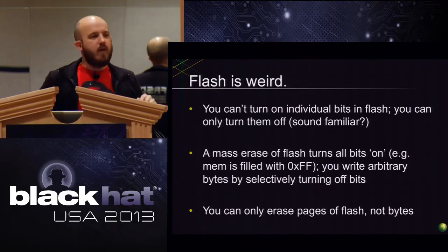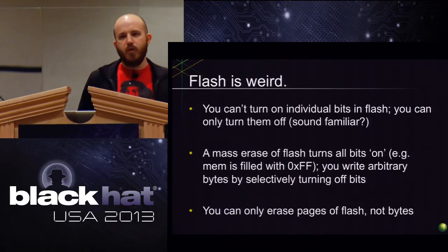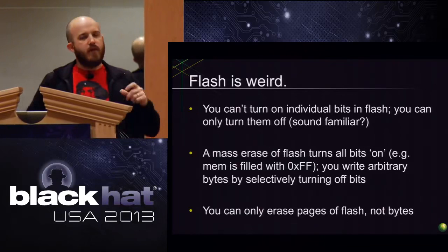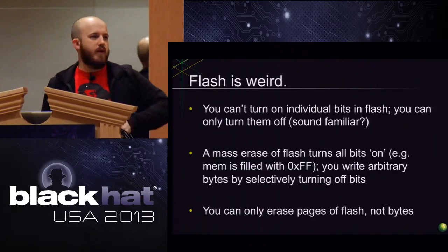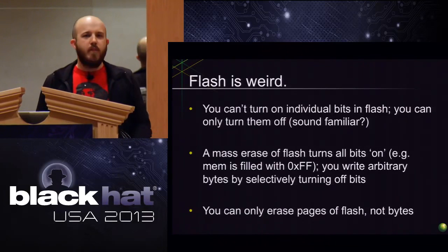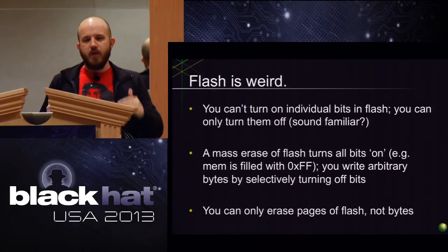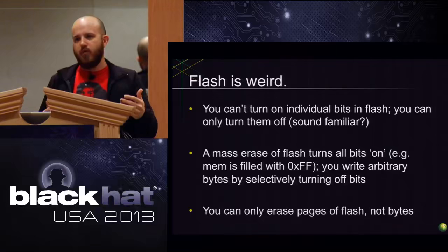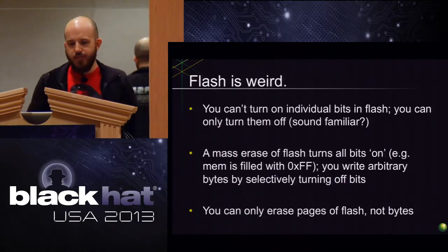So what that means is that if you want to make a modification, you have to reset it to FF first before you can put an arbitrary piece of data in it, or you have to find a place of code memory that's already full of FFs. It's very different than normal RAM or what we think about on hard drives, where you can just push something and say go do that. If you don't know what you're doing and you don't know the state of it beforehand, then random writes will just fail because it can't create that state, right? Because it's all a series of which bits are turned on and which ones are off.